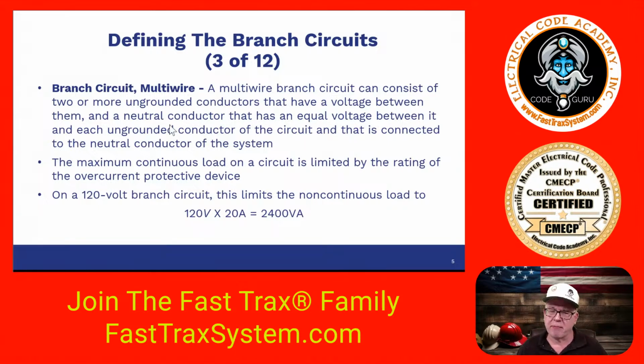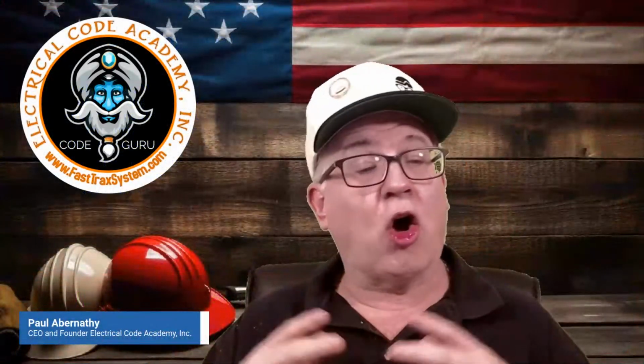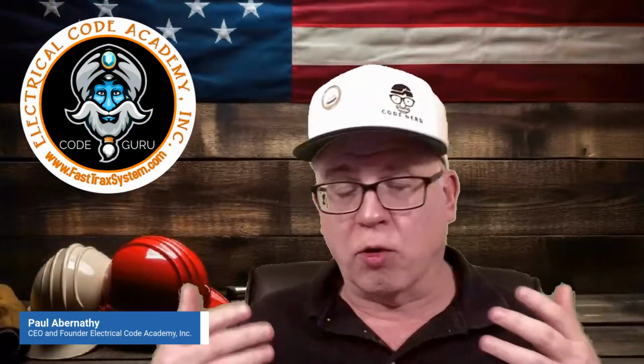Now, as you see up here, the maximum continuous load on a circuit is limited by the rating of the overcurrent device. So what is a continuous load? Well, don't worry. We're going to look at an understanding of a continuous load, but it's so important for people to realize that on a branch circuit, we could actually load that circuit all the way up to its wattage value or its VA value.